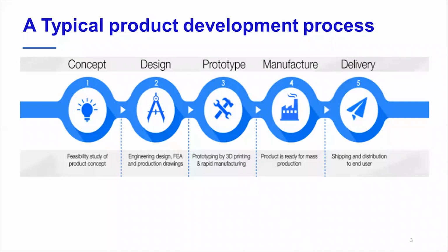Typically you work on the concepts. You bring together all the concepts, then you choose a few concepts, some 2-3 concepts. I'll talk over how typically people choose the concepts out of 10 concepts, let's say. We'll talk a little more about that later. So you pick a concept, now you start working towards design. You work on primary design, just an outline of the bracket. You try to decide your dimensions, your angle, your rib width and size. But this is at primary level, not really very detailed. And then you take that and get your prototype.